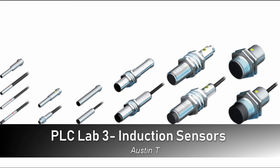These applications can be used in, for example, a conveyor belt carrying a part down, and that part trips a sensor. We're going to be simulating that today, except the user will be pressing a start button to begin the process, and then the part will be carried down to the induction sensor. The sensor will trip when the part passes by it, and it will stop the whole process. Then the user has to press the reset button, and the process can begin again. Let's see how it's laid out.